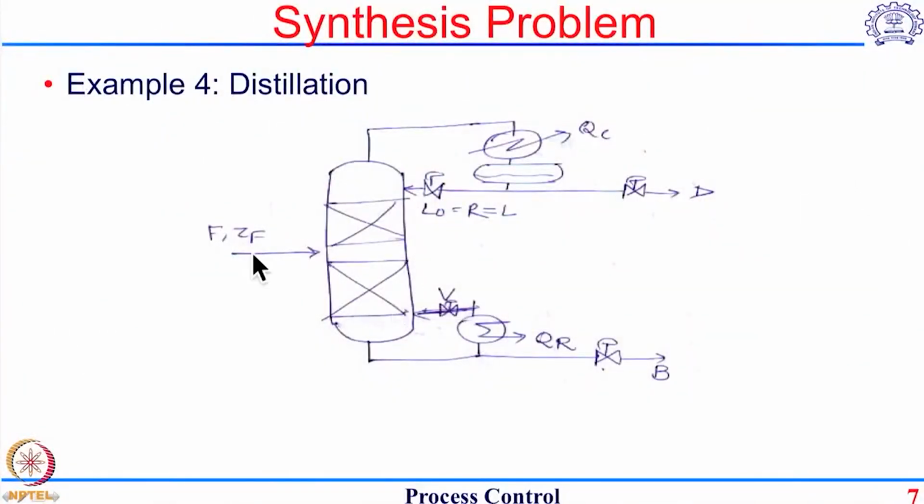So as we can do this for all sorts of example systems, and what I want to drive at is, so let us say if you take a distillation column such as the one shown here, you will see that the distillation column has 5 controlled variables. If this is a binary distillation column, you will have some control of the purity here at the top, purity at the bottom. You also have two liquid holdups, 2 liquid inventories in the system. One is the reflux drum level and the other one is the reboiler or the bottom of the column level, sump level. And then lastly you have to control the vapor inventory which is given by the pressure control.